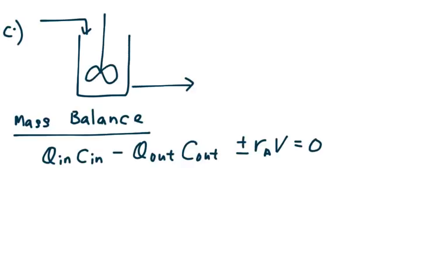Now part C says that assuming ideal conditions, which reactor, a PFR or CSTR, will require lesser volume to achieve the same conversion. So what you need to do is, given all the parameters, now you have to assume that you are running this system using a CSTR. So using mass balances, the flow rate into the system is 60 meter cube per day.